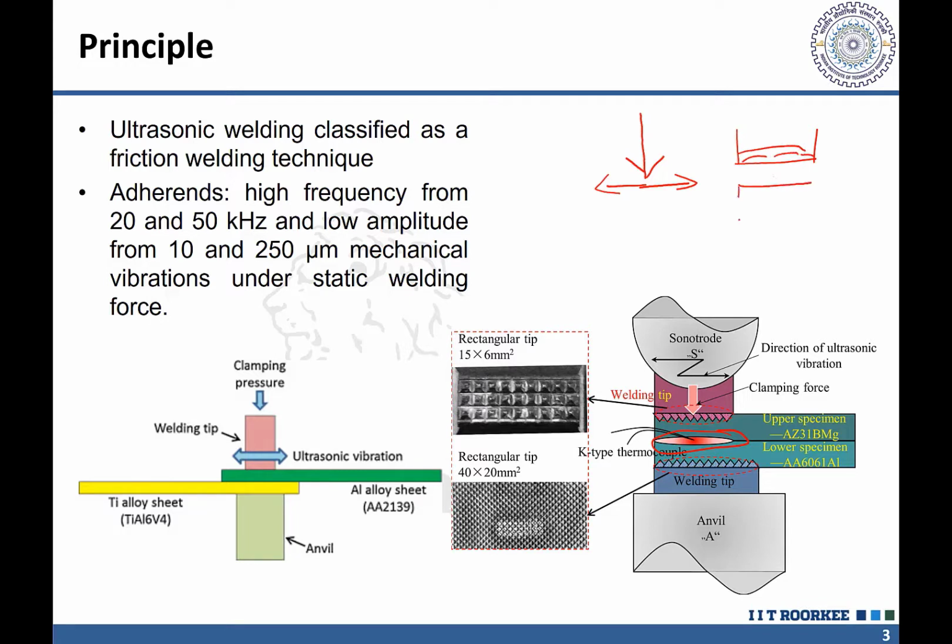Similarly, the surface of the other side is also getting softened, and these are experiencing the shearing movement. So softening, sometimes coupled with localized melting, will be leading to the intermixing of the metal from one side to another, like the metal from one side getting mixed with the metal of the other side. That is what we will see more clearly in the next diagram here.